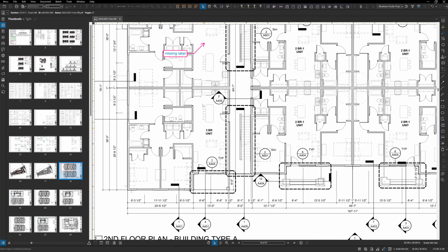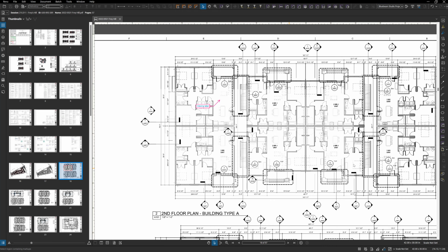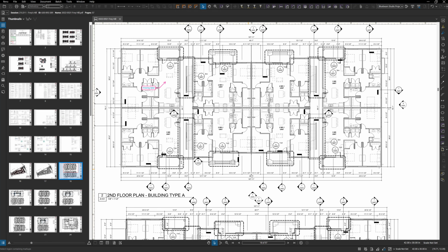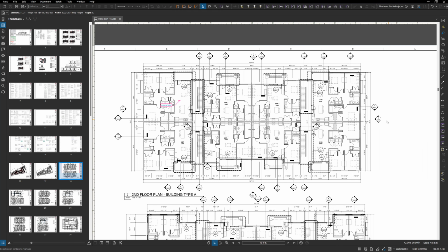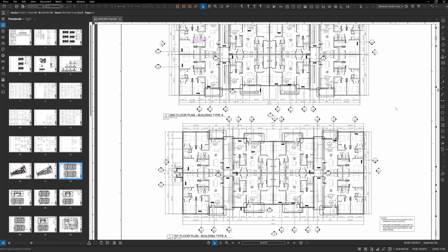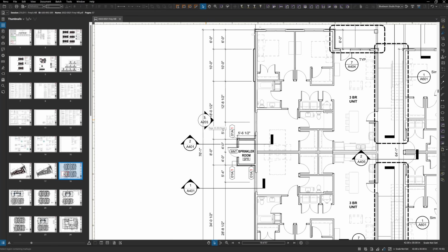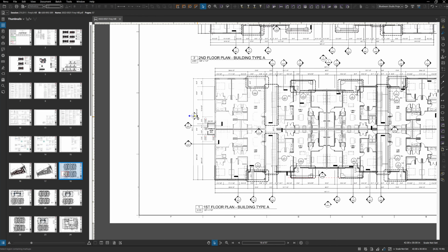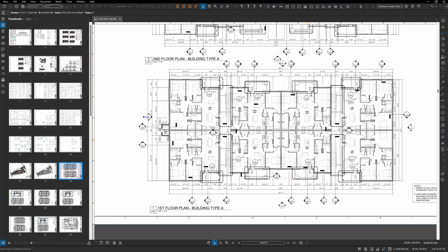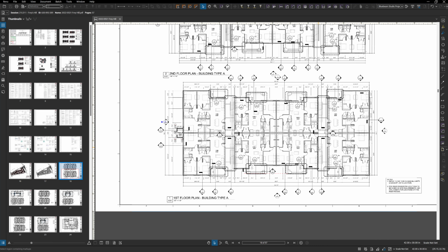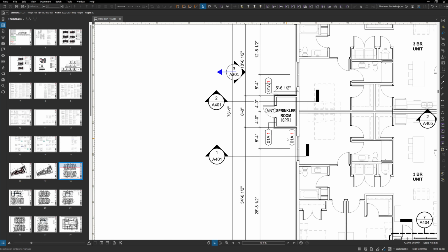From there, it's nice to see call-out tags. Where do I go look for the stairs? Where do I go look on how to build the porches? Are my section tags called out? Do I have all my exterior elevations in the viewports? Are they easy to read, or are they sort of covered up or sort of in line with something else? You know, that's that level of drafting cleanliness. Do the title blocks line up? Or are we at 1/8 of an inch per foot scale? If not, why not?